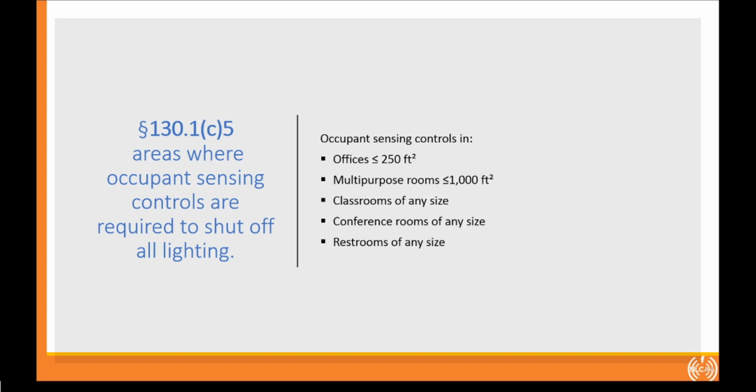Most people won't feel the need to go to the manual switch to override and raise the lights. Most folks will be okay with that lighting, and if that is the case, then it's a win, because we're saving anywhere between 30 to 50% lighting power right off the bat, simply because you have enough lighting in the space and you don't feel the need to override the lights.